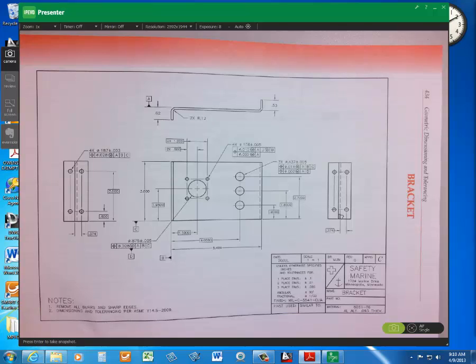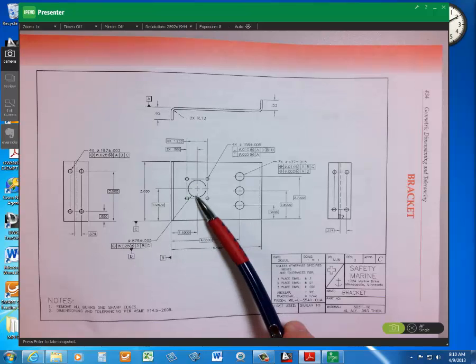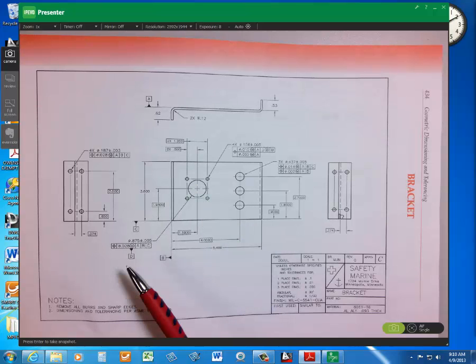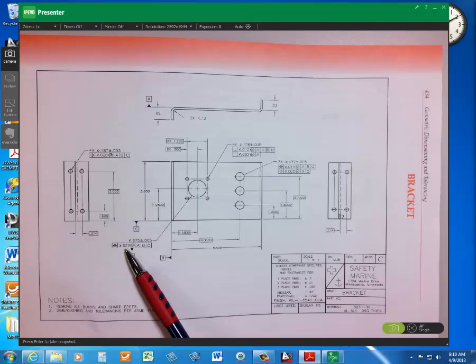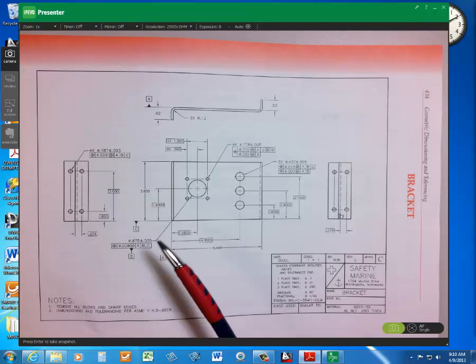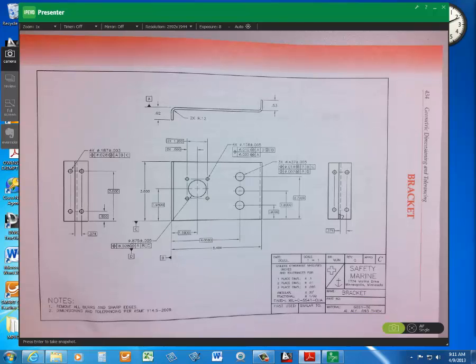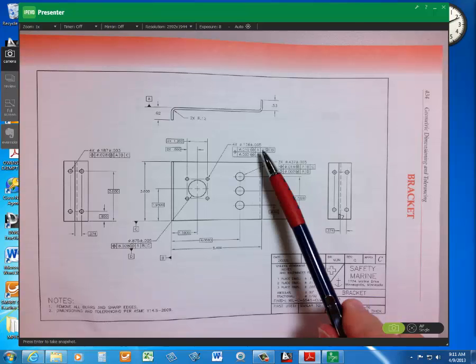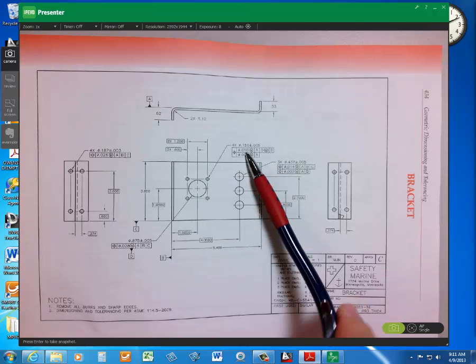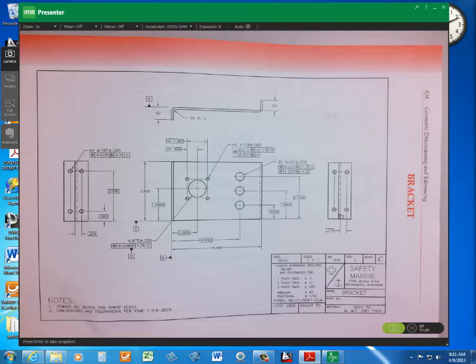So when that large hole, the axis of it is datum D. So when it is 14 thousandths of an inch over to the right, let's say it's been produced and it's over to the right, then this pattern as a group of holes can be over 14 thousandths as a group.